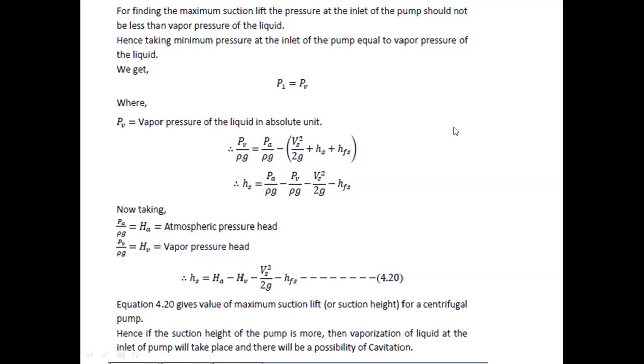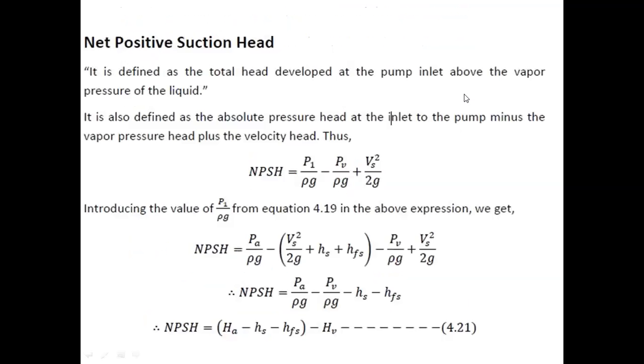Hence if the suction height of the pump is more, then vaporization of liquid at the inlet of the pump will take place, and there will be a possibility of cavitation. This condition is applied for cavitation.